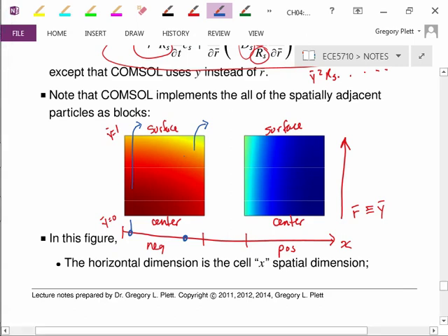In the positive electrode, the ratio of the conductivity of the electrolyte and the solid are different from the negative electrode, and so it operates a little differently. And in fact, almost all of the initial discharging of this cell contributes to changing concentration right near the separator, and very little gets here.